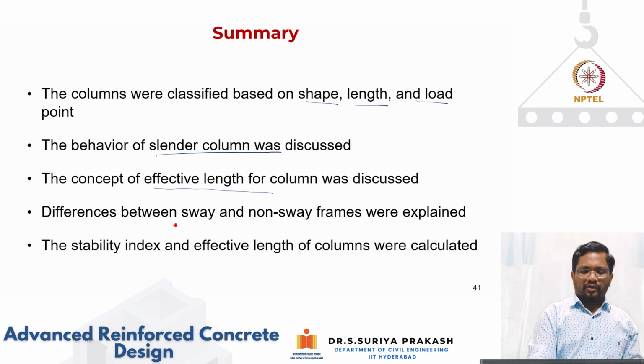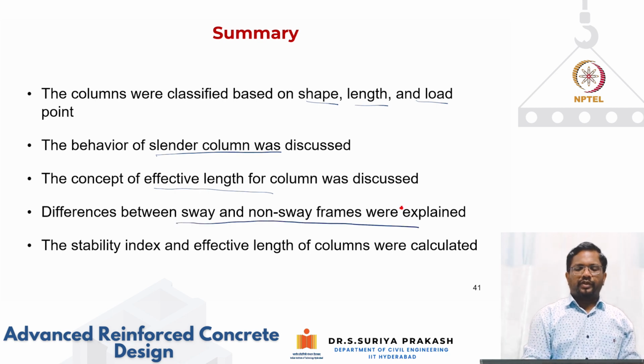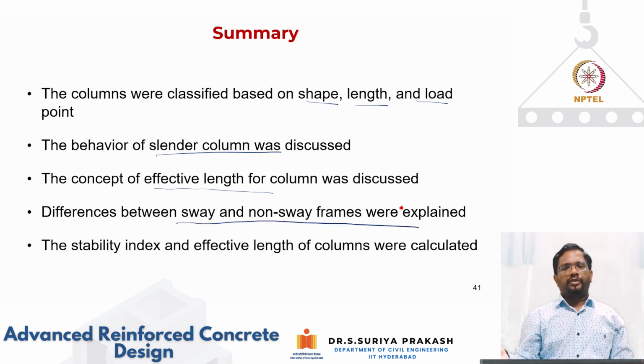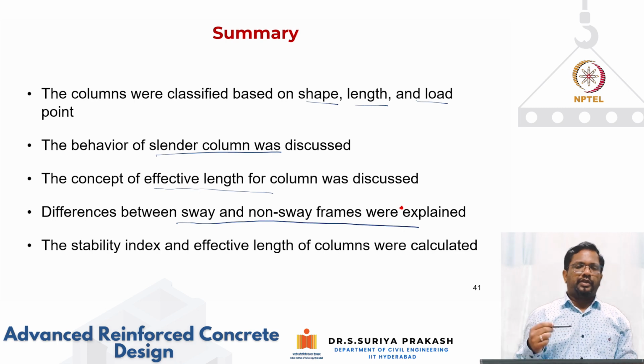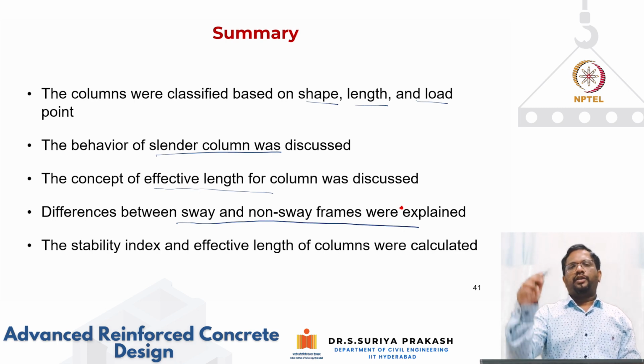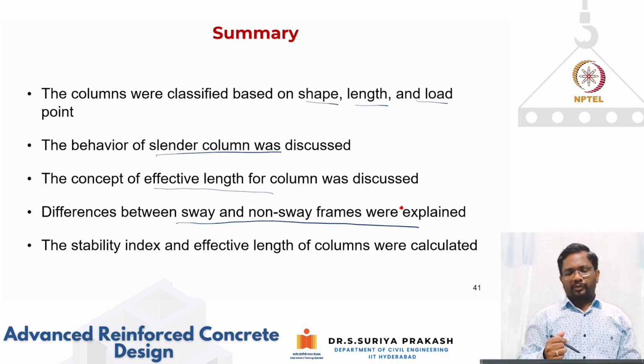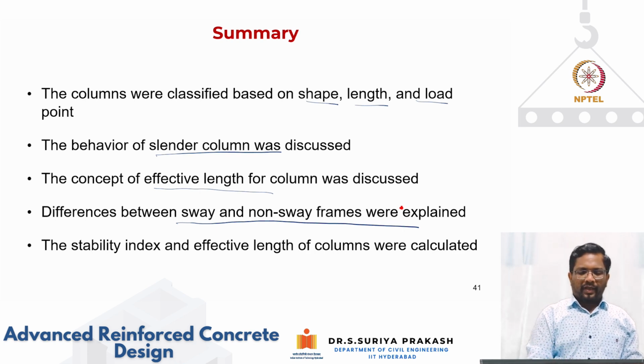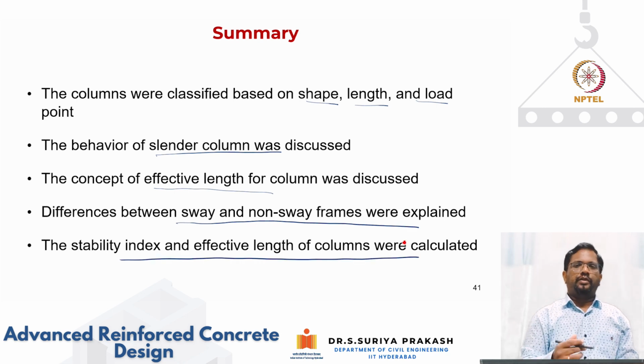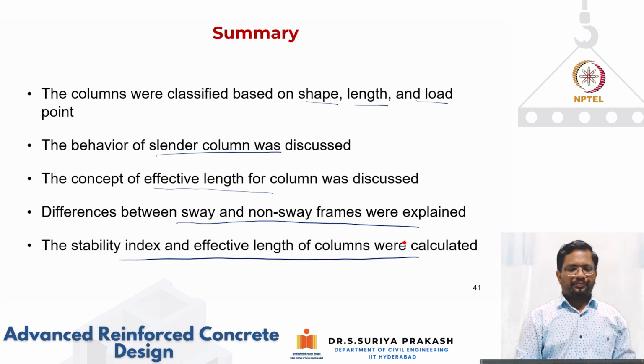And then we also talked about the difference between sway and non-sway frames. We distinguish the frame as sway or non-sway by calculating the stability index. For calculating stability index, again we have to use the lateral flexibility. Again we derived the expression for lateral flexibility, and we also calculated the stability index and effective length by using an example.